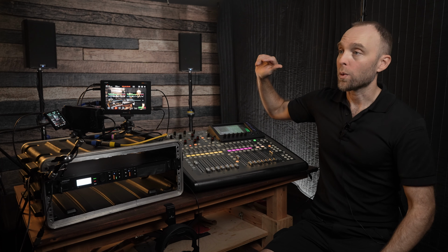All right, so I'm going to regain structure this system from scratch 2 ways, and we'll listen to the results of those gain structured systems as that audio gets recorded over to this Blackmagic Video Assist, and again, structuring for volume levels coming out of those speakers. In the first method, I'll gain structure backwards from the speaker, and I'll limit the volume of the speakers with preamps. And in the second method, I'll work forward through the system. All right, here we go.